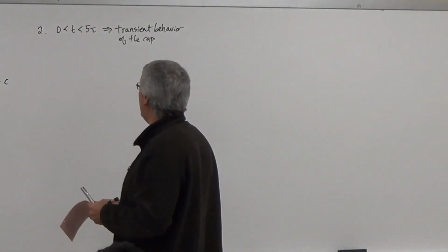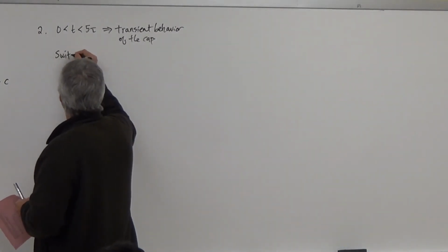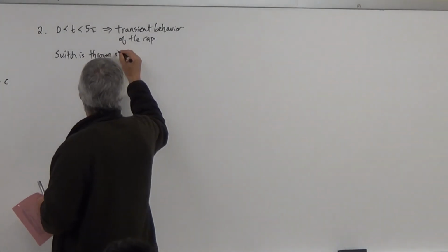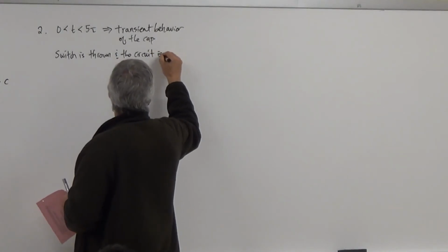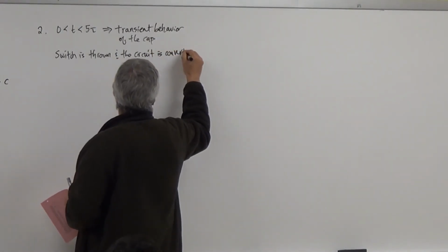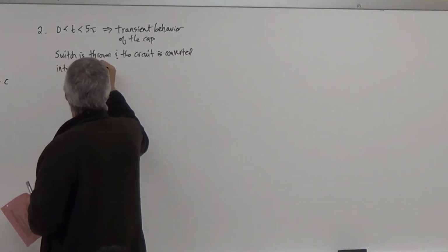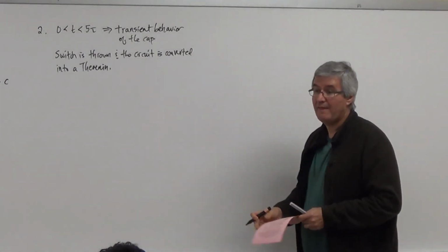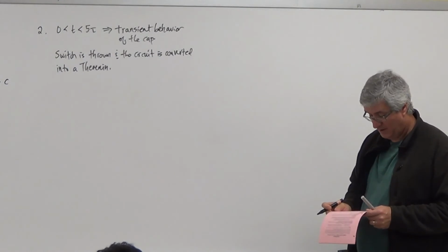So what happens in this period is that the switch is thrown and the circuit is converted into a Thevenin. Okay? And then that's the equation that we actually go after and solve.